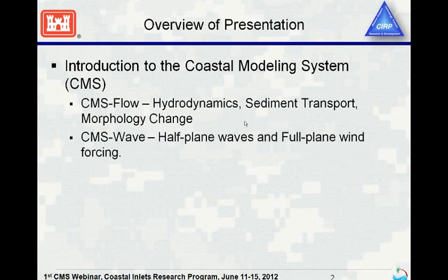CMS-Flow, like I said earlier, governs the hydrodynamics, the sediment transport, and morphology change. There's a simple salinity transport as well as some other features that we're working on implementing. There's CMS-Wave, that's a half-plane wave model. It also has a full-plane wind forcing, so that if you have winds coming in that oppose the direction your waves are coming in, it can handle that. I'll be going over that in a little bit.